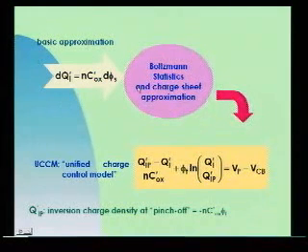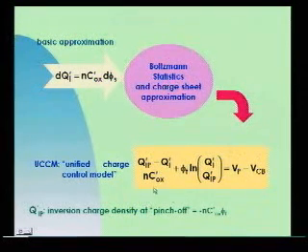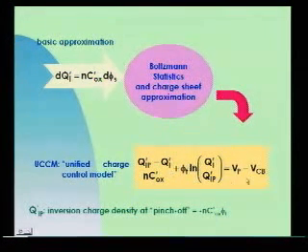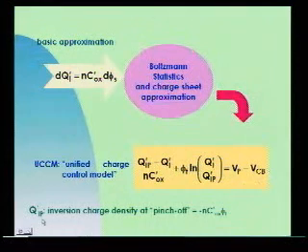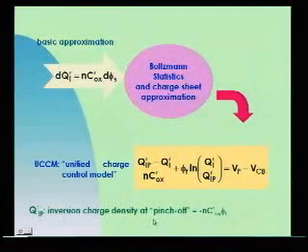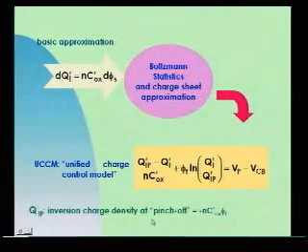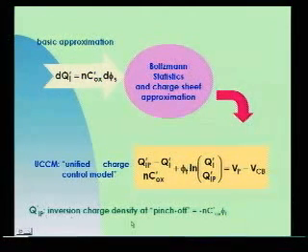But applying the same approximation, we have a physical derivation of the UCCM model. And the UCCM model relates the inversion charge density to the terminal voltage. Okay? Then there's a parameter that appears here that is the inversion charge density at pinch off. It can be set arbitrarily, but ACM uses this value. It's a good value for the inversion charge density at pinch off.